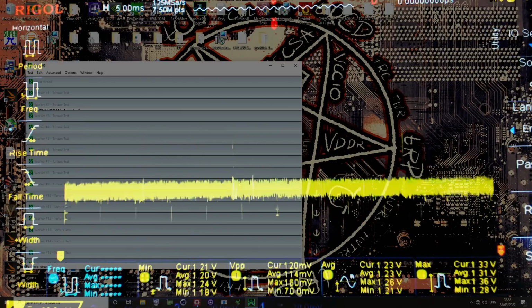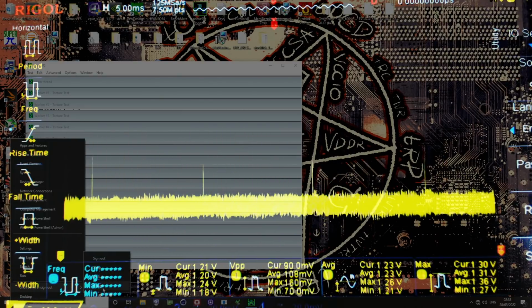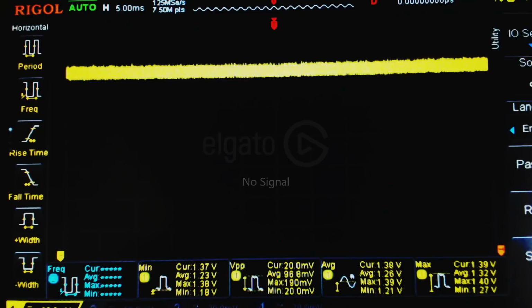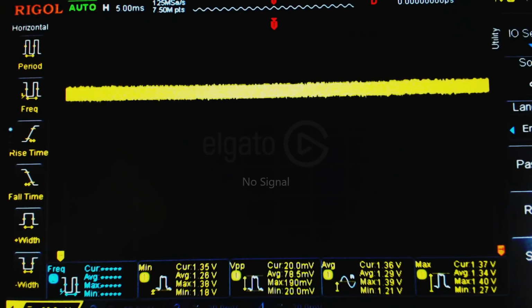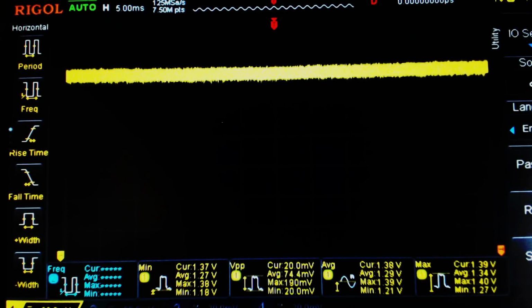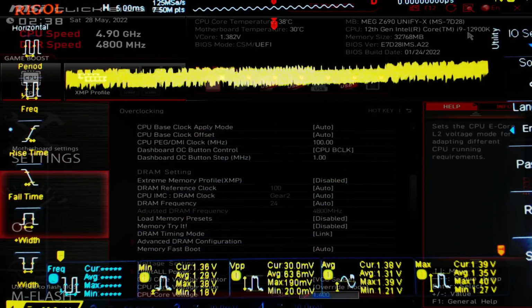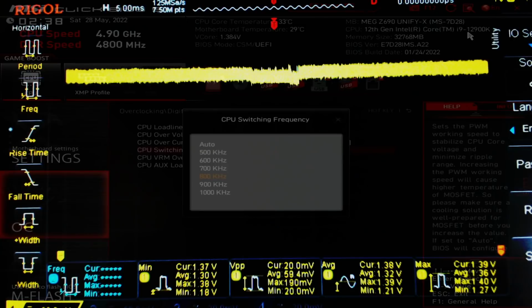I have no idea what the board is doing. Yeah, okay. Already on the Torpedo EKX, which, admittedly, I didn't test all the way out to its droopiest LLC setting, maxing out the switching frequency, or even just raising it at all, is just a terrible idea, based on my testing with that board. But this right here is something else. This is so bad.